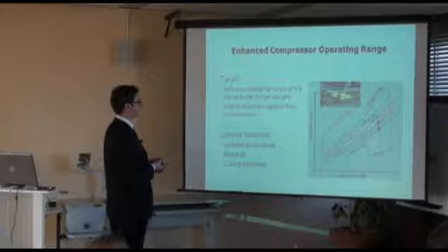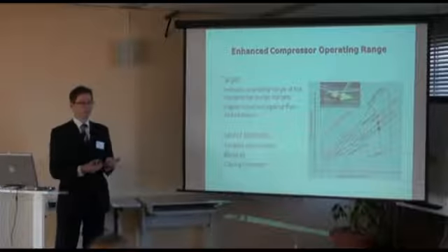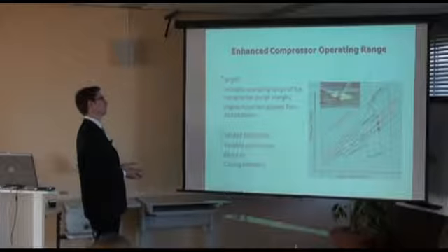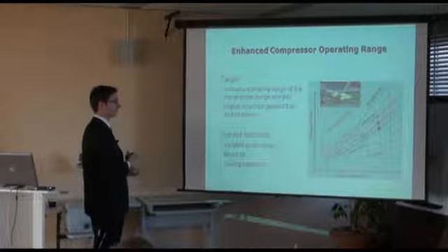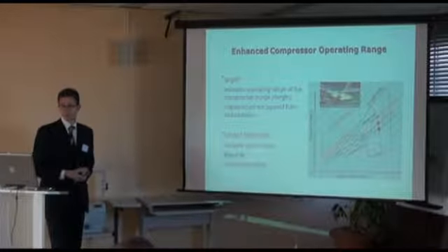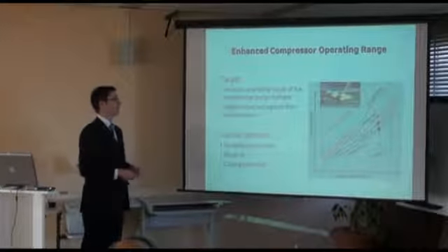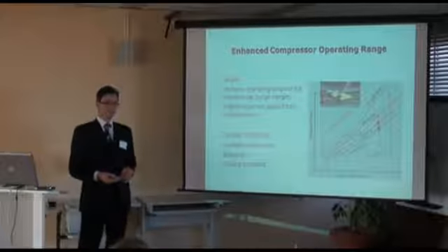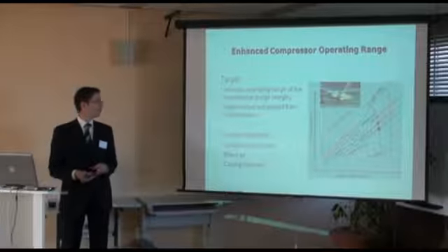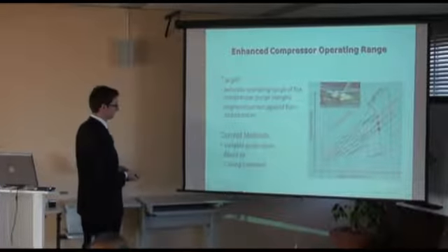So today the status is that we have to keep safety margins to enable the stable operation of the engine. And what we want to do is that we want to do that actively. So actively increasing the operating range of the compressor and also making it more tolerant against disturbances. And once we have that technology which can actively increase the operating range, we can change the design of the compressor. And this will give us an efficiency benefit and a weight benefit. So this is very interesting for new engine designs.